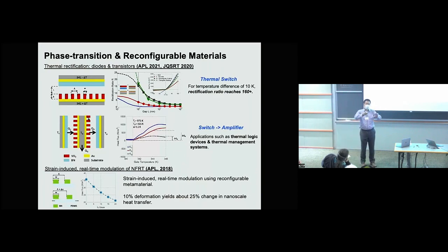Now if you have 2 thermal emitters and place them back to back, it creates a 3-terminal structure, right? So 1, 2, and 3. This gives us an idea. It's a transistor-like structure, so maybe we are able to demonstrate transistor-like phenomena. In this work, we also designed a non-contact mode radiation-based thermal transistor, which we published a few years ago in APL. That's our first work, and this one serves as a fundamental for our other work.